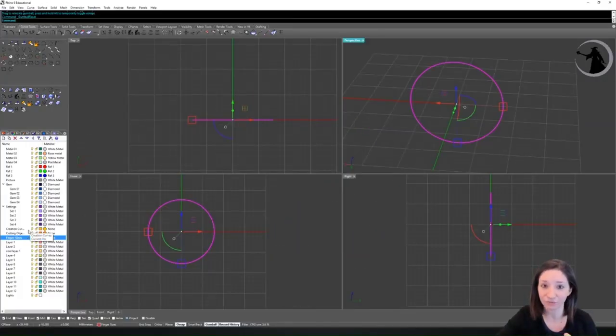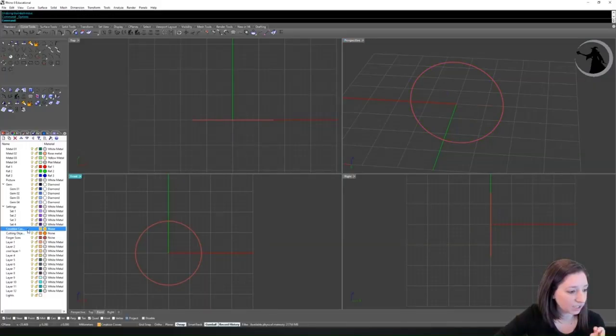We're going to make this ring with what we call a sweep, which is a surface tool. I'm going to change to this kind of orangey layer that's 2 above the finger sizes in the one I gave you. You can do everything in the same layer color if you want. I don't recommend it.